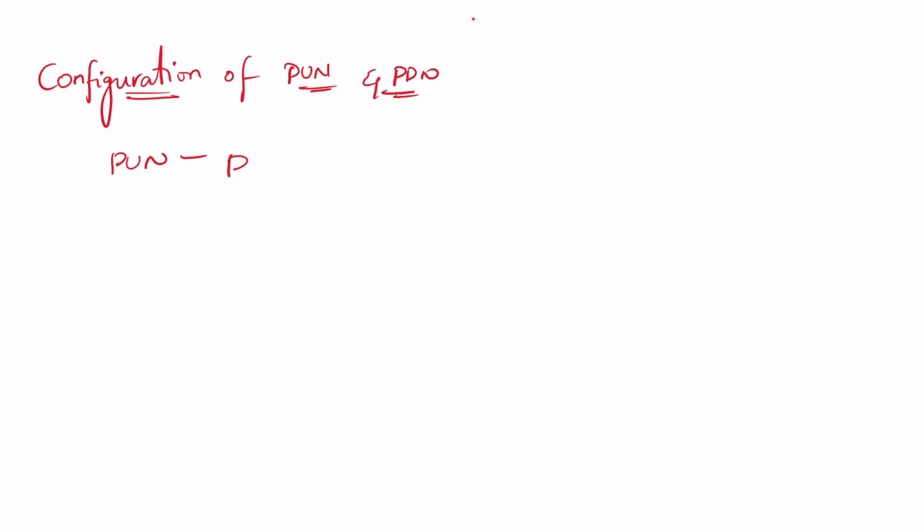Okay. So the pull up network consists of PMOS. The PMOS transistors are contained in the pull-up network. For AND operations, if the equation is like A dot B, so between A and B you have an AND operation. For that AND operation, the PMOSs are going to be connected in parallel.